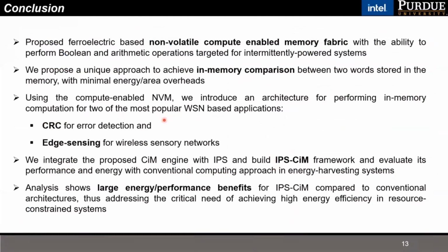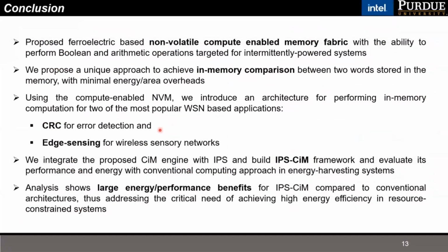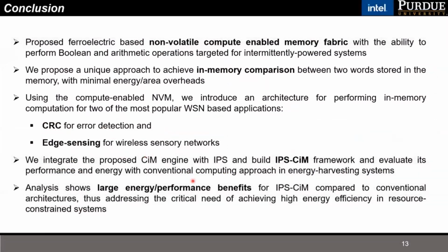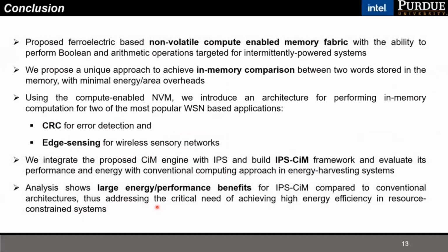With that, I'll conclude my talk. We propose ferroelectric-based non-volatile compute-enabled memory cells to perform Boolean and arithmetic operations, especially targeted for intermittently powered systems and their workloads. We look at two specific workloads, which are cyclic redundancy check for error detection and edge sensing for wireless sensory networks. We observed excellent energy and performance benefits for the IPS SIM engine compared to conventional architectures, and therefore addressing the critical need of achieving high energy efficiency in resource constrained systems. Thank you.